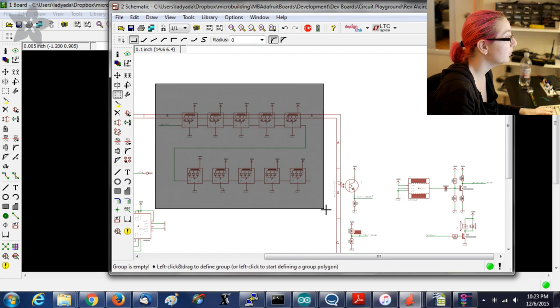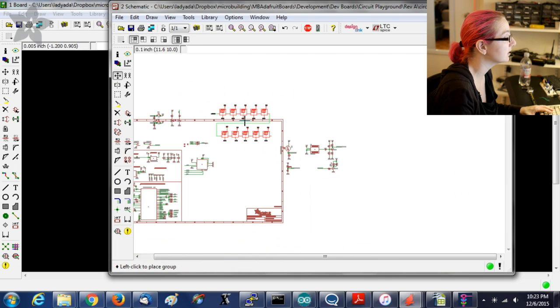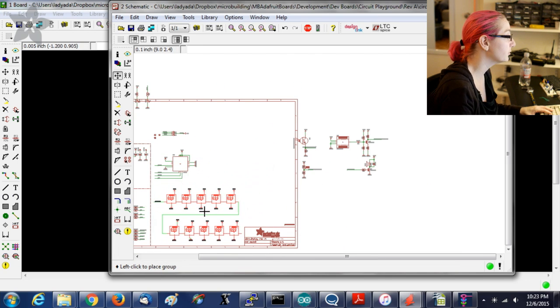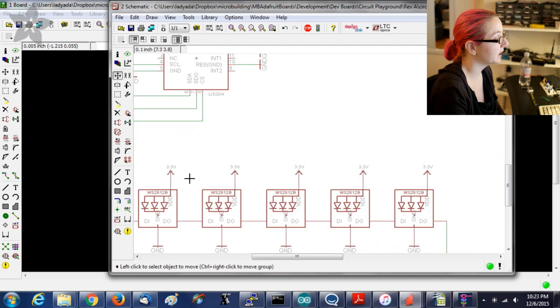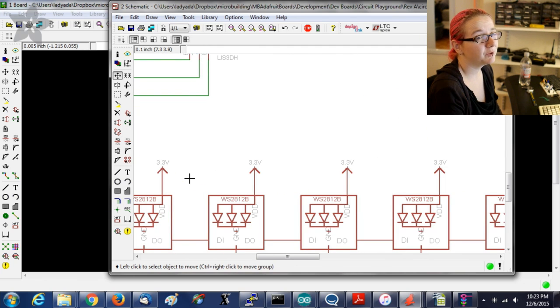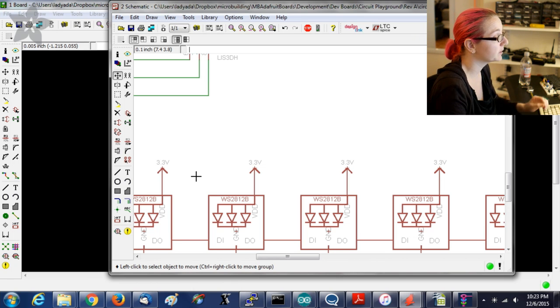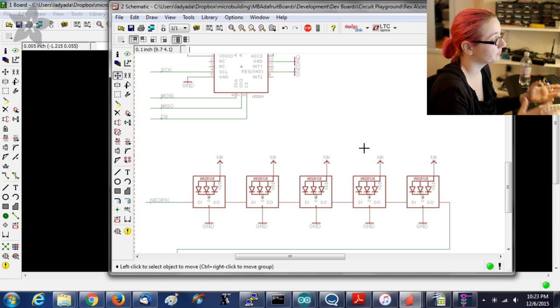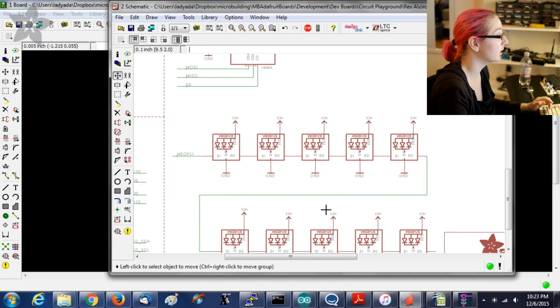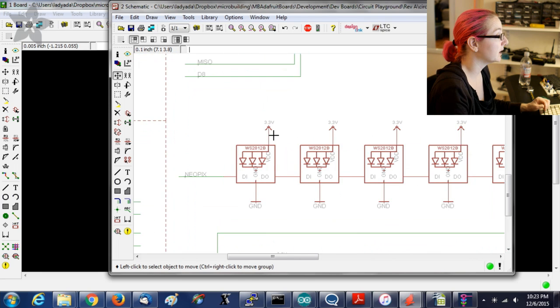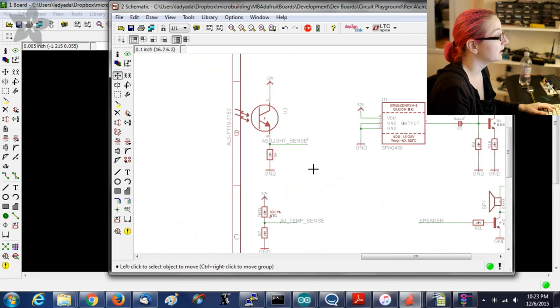Now you're probably saying, hey, wait a minute, blue LEDs and also white LEDs have a forward voltage of 3.4 volts. Don't you need to have it be higher than 3.4 if you wanted perfect color reproducibility? But I actually don't care. And I've also noticed that at the currents that the NeoPixels get driven at, 3.3 volts is fine. You get all the color that you want from them. So the NeoPixels are driven from the 3.3 volt line.